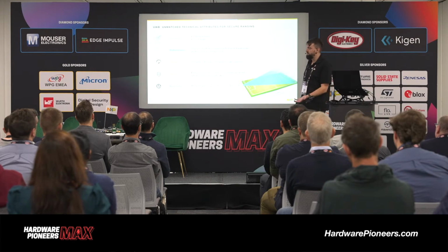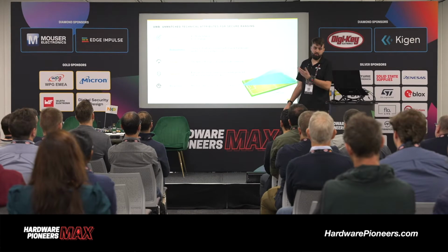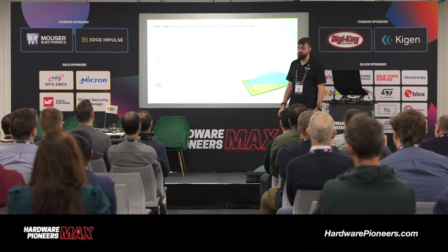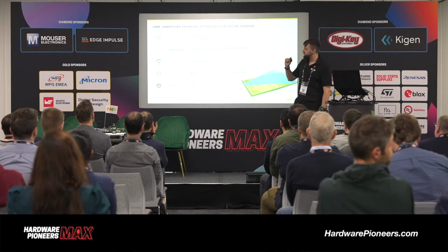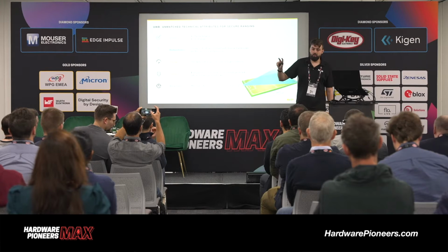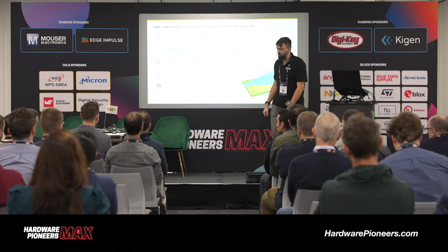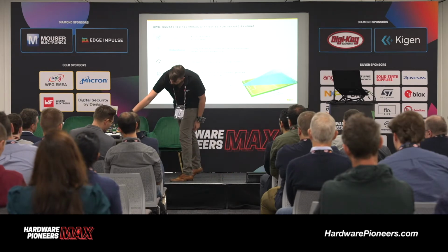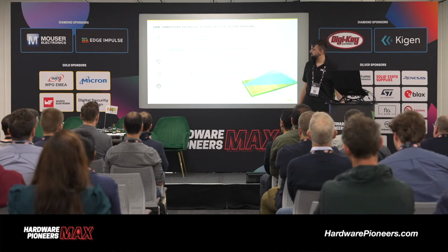So the best feature of ultra wideband, the part that excites me the most, is of course this time of flight measurement. We have an accuracy of ±10 centimeters, and we can also do angle measurements of ±3 degrees with multiple antennas, as you can see on the device on the rover here in the front. There we have multiple antennas with which we can do PDOA, but let me get to that later.